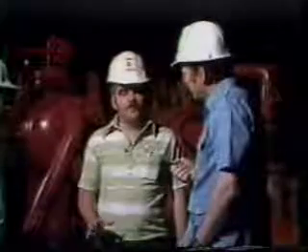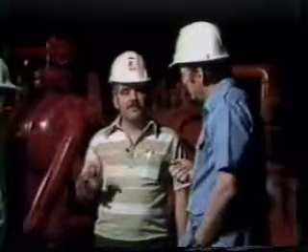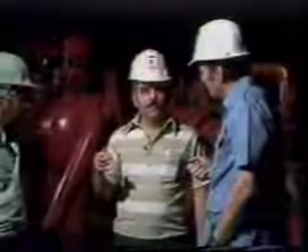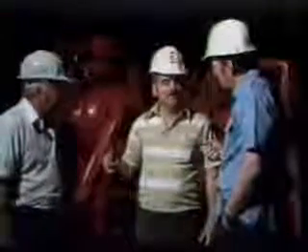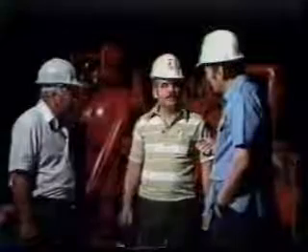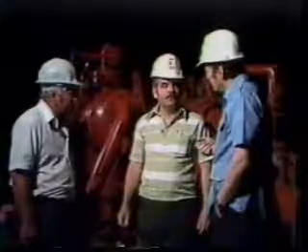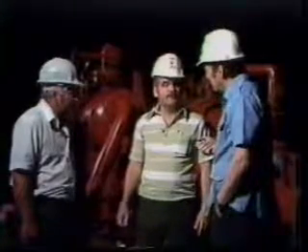Okay, now for your corporate purposes, you're going to go beyond that. That is correct. We will run a 4-point test, which means we'll start at the highest rate, which will be in the range of hopefully 3 million a day, and take different measurements at different flow rates, probably 2 million and 1 million a day. This will help us to determine the extent of the reservoir, the deliverability of the well, and will help us in later engineering studies.